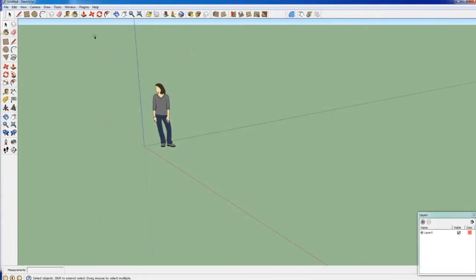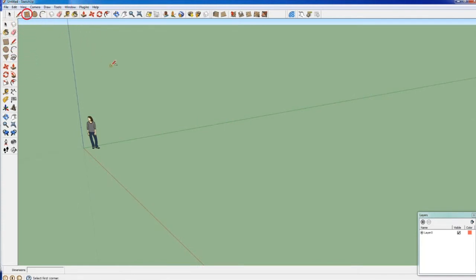So now we are ready to start making our first object that will actually be the bottom of the auditorium. So we will start by making a rectangle. We take the rectangle tool, the shortcut is R on the keyboard, and we go so close to the origin until it's snapped and the color turns yellow. So we click and we start pulling away in the desired direction.